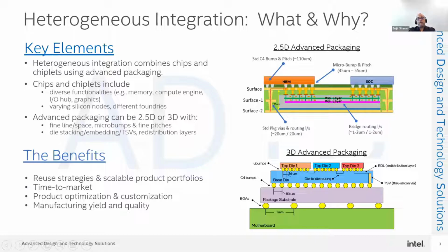We drive both signals and power and ground through the bridge to essentially create a full network across the HBM and the SOC dies. Obviously, it involves die stacking, embedding the TSVs, the distribution layers, and so on. It is an interesting challenge, as you have to co-optimize across both the chiplet dies as well as the chiplet signals which come out directly to the package. In this case, the reason we call it 2.5D is you have signals which come out directly to the package from the top tiles, as well as what we call the die-to-die interconnects, which go through the